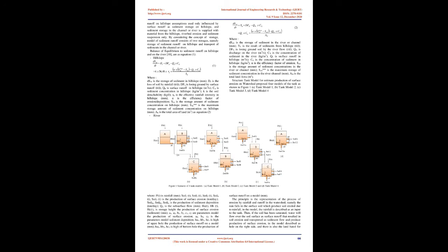Assuming that surface erosion and sediment transport based on rainfall events are only influenced by surface runoff, and considering the concept of the type of storage, in this paper one black box approach is presented which connects the factors that cause erosion and the transport processes of erosion by sediment transport using the tank model.